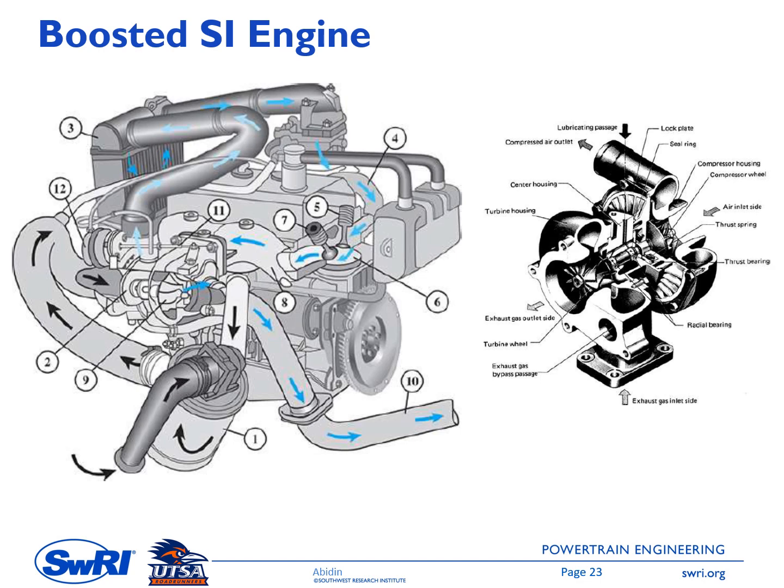This one is showing a schematic of a turbocharger. We have a turbine and a compressor on one shaft here, so the turbine shaft is connected directly to the compressor shaft. In this schematic, we have point number 1 where we have the entrance of the fresh air, and it follows this path and goes to the compressor. The compressor compresses this gas, increases the pressure, and then it enters the engine.